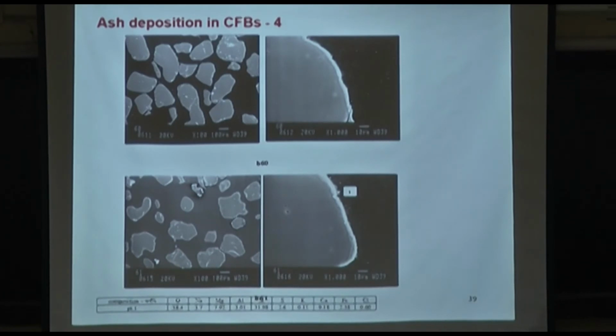And because they are fine, much smaller compared to the bed material, they will be elutriated away from the bed, from the high temperature region in the bed, along with the sticky ones, keeping the bed materials relatively unscathed. So we tested that, and then we could run that test for more than 100 hours. So we proved that particular concept in there.